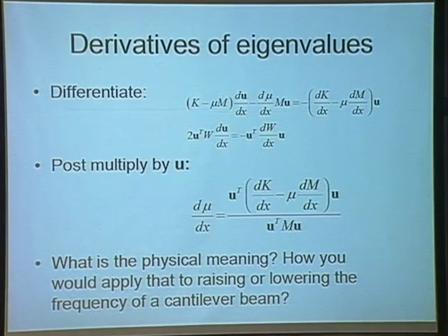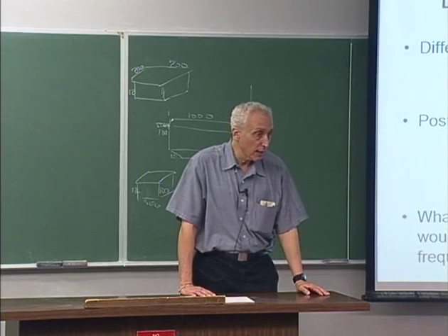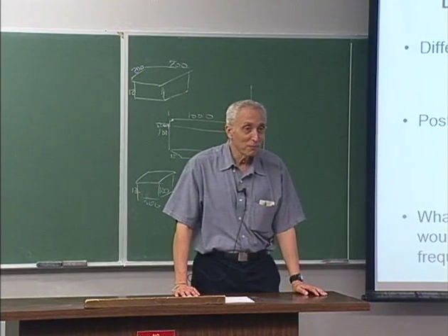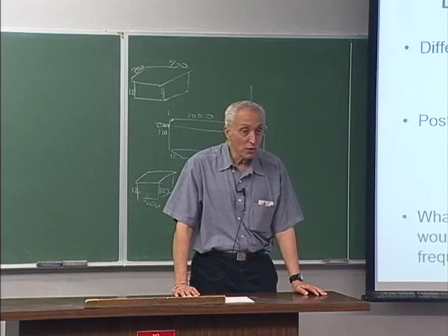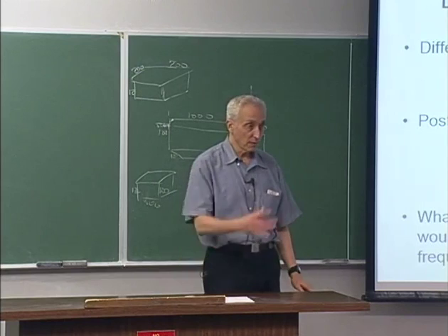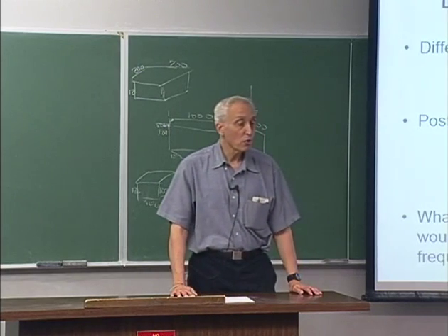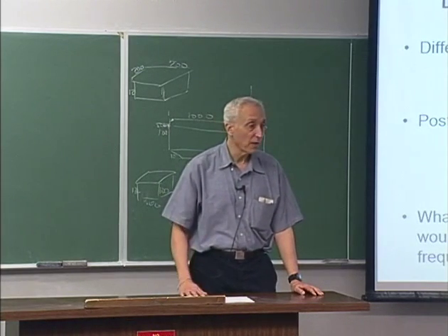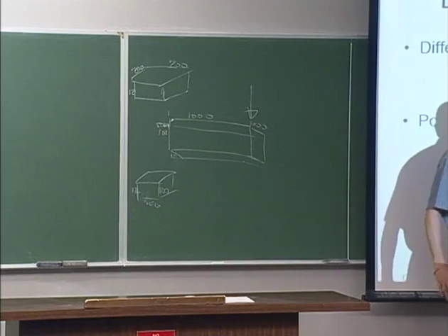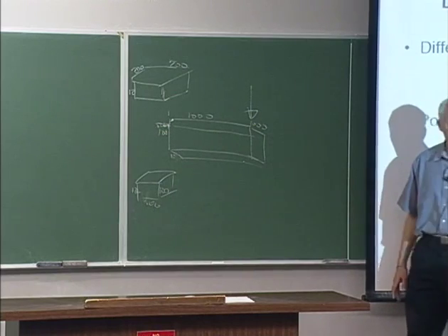So if this is big, the derivative is big. If this is small, the derivative is small. So if you are going to take the cantilever beam that you keep analyzing, and you may be sick of that beam, if we want to change a little part of that beam, that is, make it stiffer, for example, thicker, or change the Young modulus, or change the volume fraction, so that we will get big benefit from this term, where on the beam should we change it?